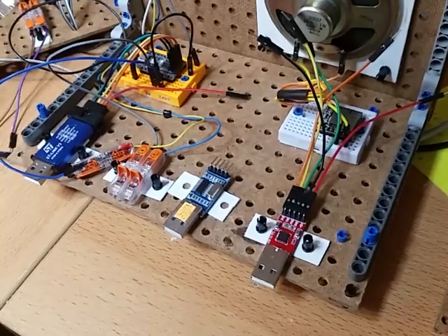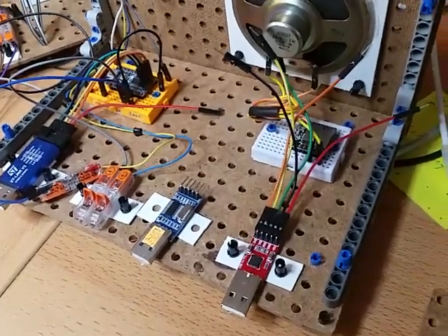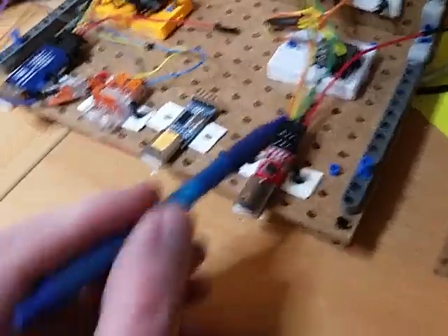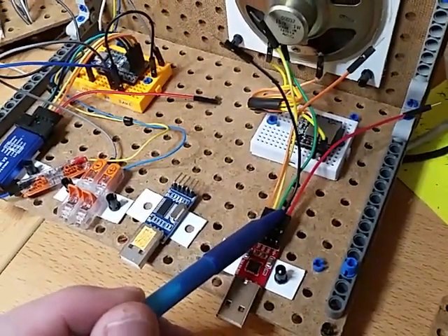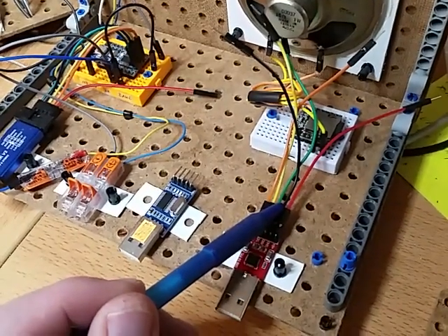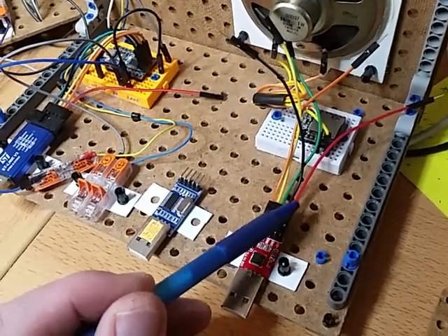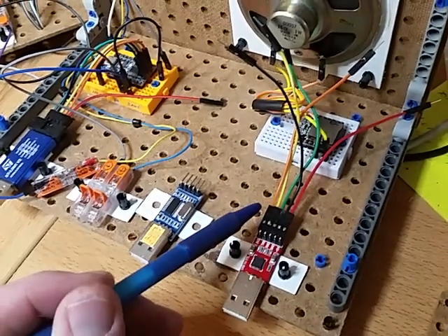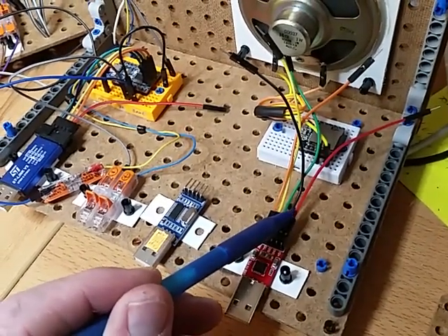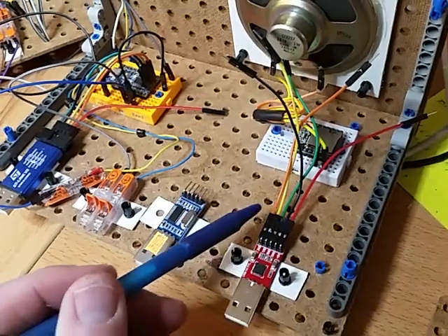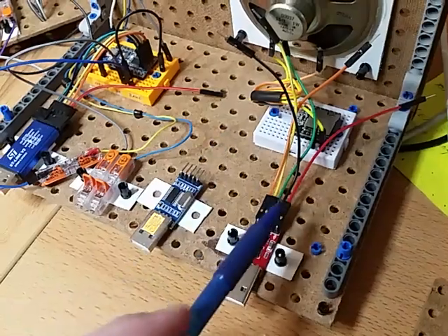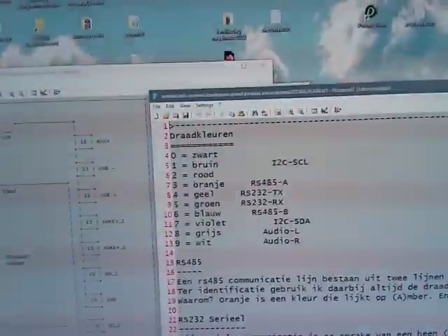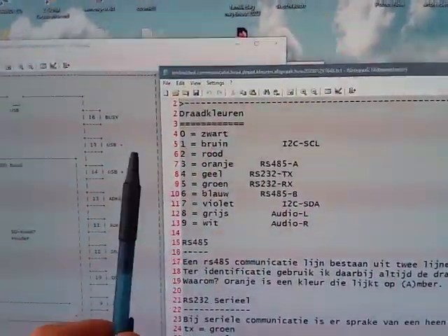There are no special rules for wire colors, but normally the ground is black and the VCC or the plus is red. But as we have 5 volt and 3.3 volt, I use red for the 5 volt and the less red, orange, for the 3.3 volt. Then I make an appointment with myself on how to use wires.